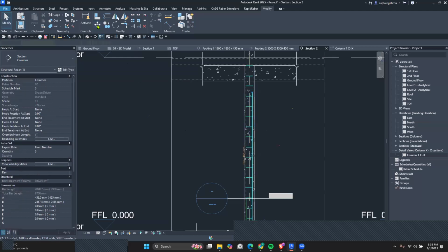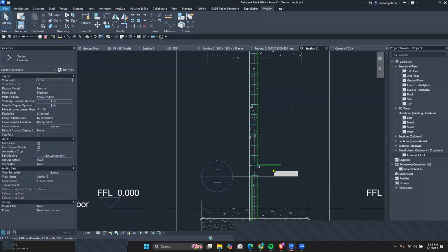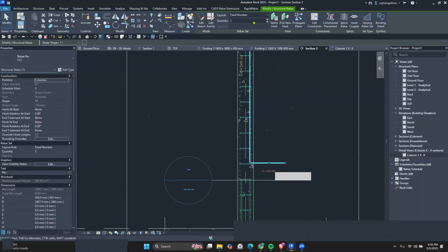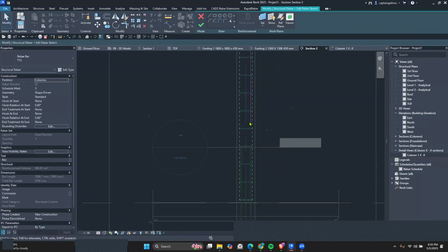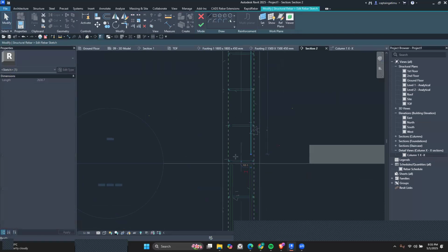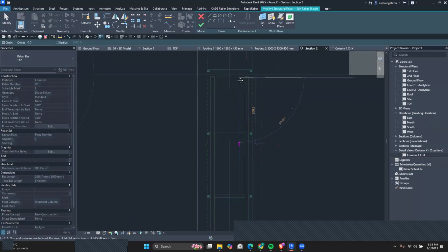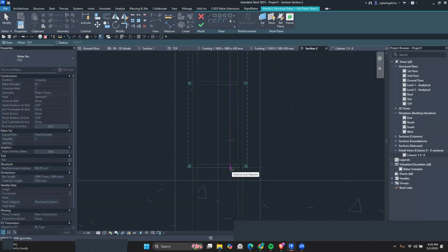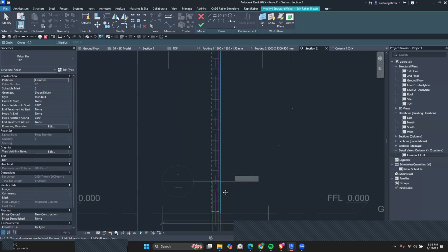Now let's move it upwards. And then after you have it in this point over here, just select it. And then once the contextual ribbon changes, I want you to click on Edit Sketch. And then let's make some edits to this. So you can scroll down here and extend it downwards. And then for the lap length, draw your second section over here and move it down. So ideally, we should have a kicker of about 75 mm where this bar should rest on, and then join it to have it something continuous.